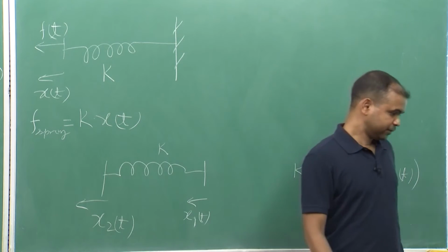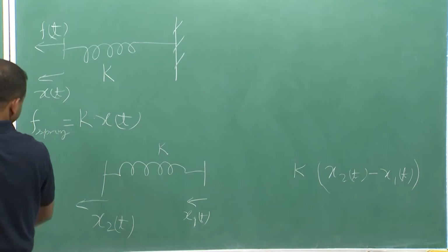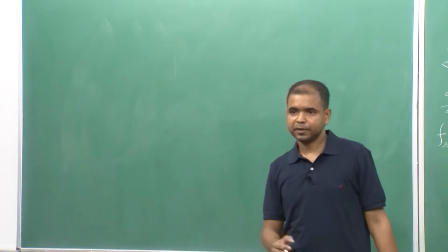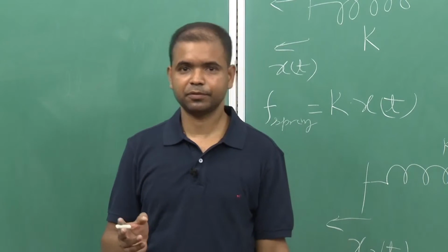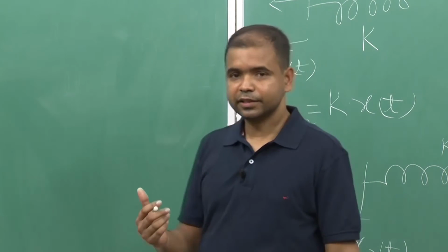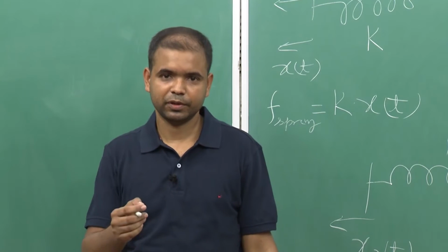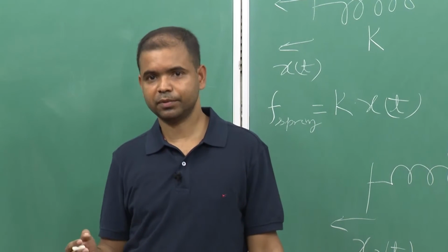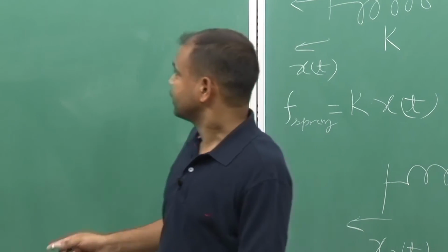The spring is also conservative in its nature, and it stores the potential energy of the system. The spring and mass are both transferring energy to each other with a phase difference of 90 degrees, but you can see the energy is conserved throughout the process. So, if there is a spring mass system and you deflect it, it will continue oscillating because there is no energy dissipating element. And the third element is the damper.